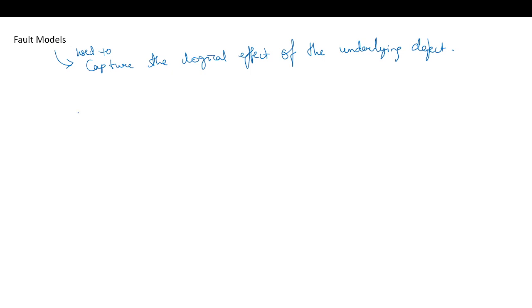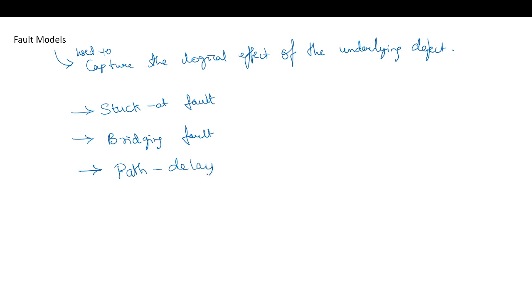We have a few fault models, which include the stuck-at fault model, the bridging fault model, and for delay testing, the path delay fault model and the transition fault model.